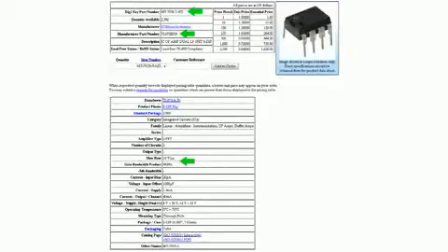The op-amp I used is a TL072BCN that I got from DigiKey. The critical specs here are a gain bandwidth product of 4 MHz and a slew rate of 14 volts per microsecond. The op-amp you use will have to have similar specs or better so that it can operate as an oscillator well into the megahertz range. It will also have to be able to handle at least 9 volts.